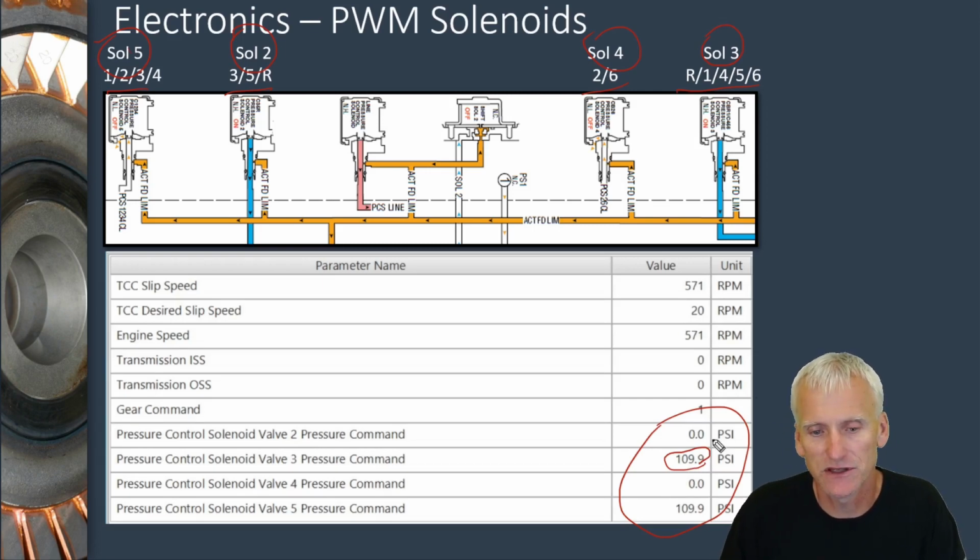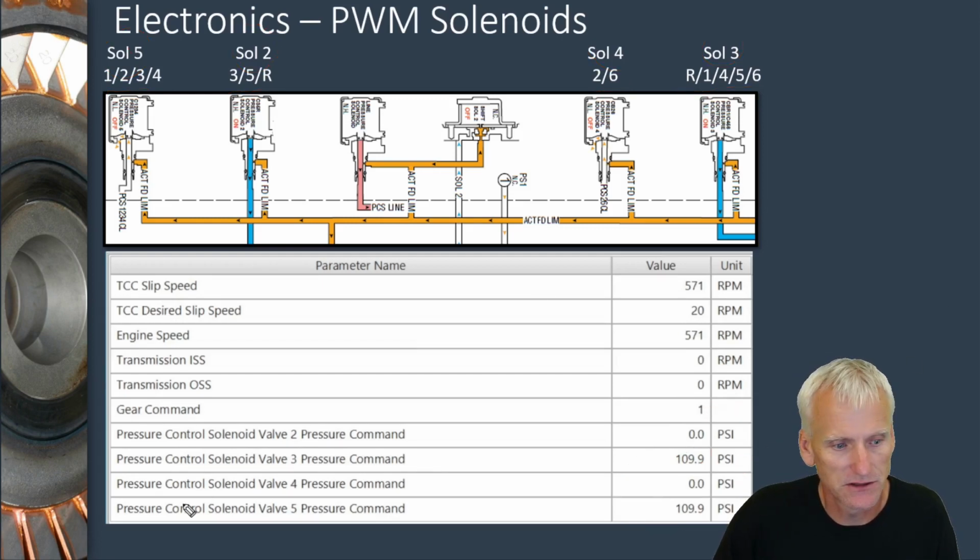The only information they've got input-wise on whether or not these things have any pressure are those pressure switches that we looked at on the input side of things. But those things close at a lower pressure. They don't close at high pressure. And they're not sensors, so they don't tell what the pressure is. They just show whether or not there was pressure there and it achieved their minimum amount. So let's look at this video and see if we can kind of follow along.